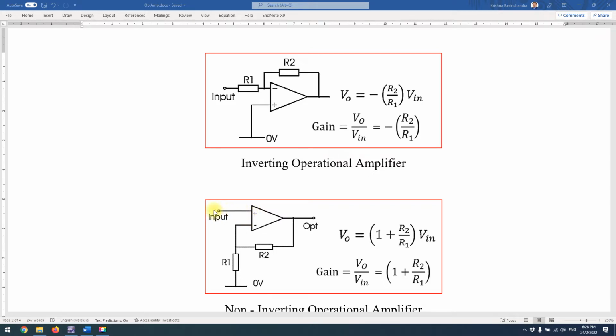My mistake. Pin 3 is now connected to the input, which is the function generator. Pin 2 remains there, but instead of being connected to the input, it's grounded. The connection of R1 and R2 is the same as the inverting side.